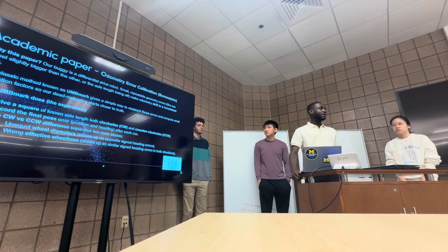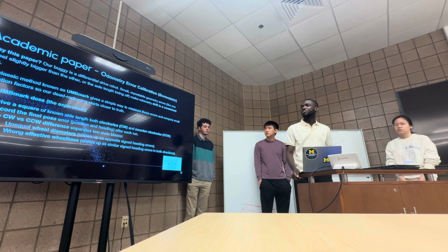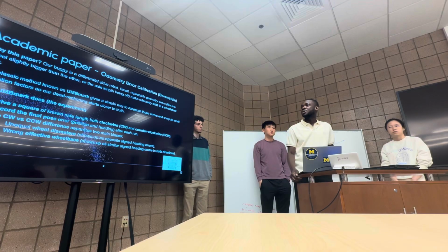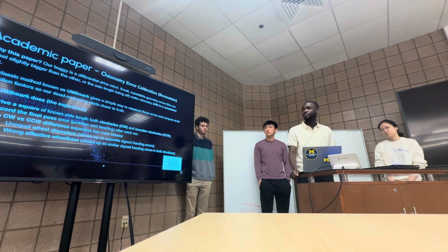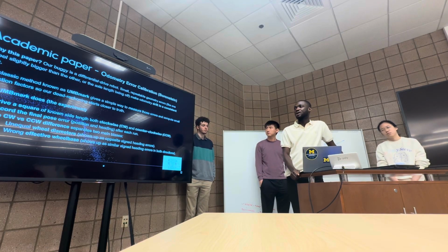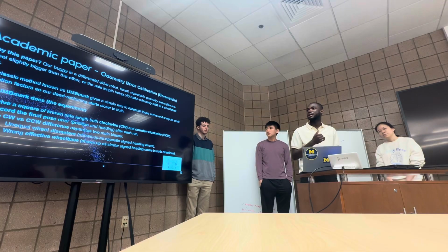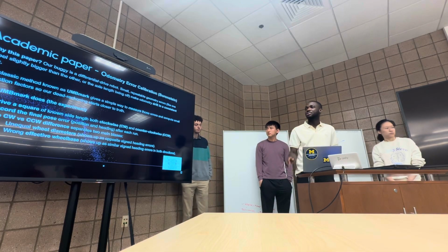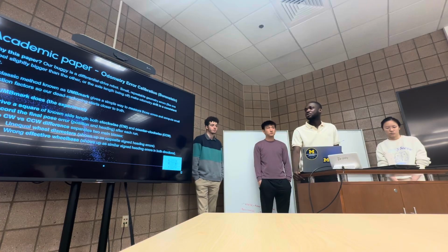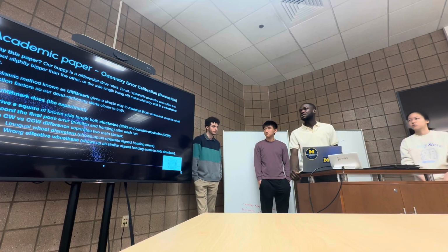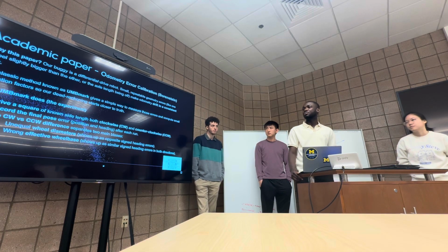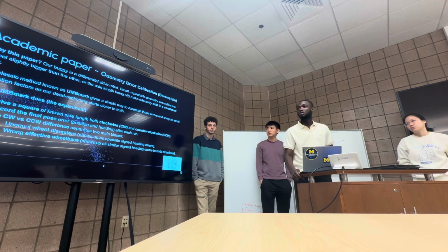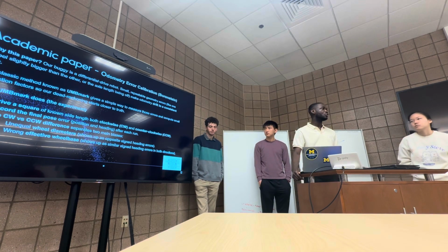Okay, so based on our design, we looked at some papers to see how we can solve some issues we might encounter with odometry error calibration. Our design is based on a buggy differential robot, so there might be errors from small repeatable geometry errors, like one of the wheels being slightly bigger than the other, or the axle length being off, making the odometry drift inconsistently. There's a classical method known as the UMBmark, which gives a simple way to measure these errors and compute small correction factors so that our dead reckoning stays closer to the truth.